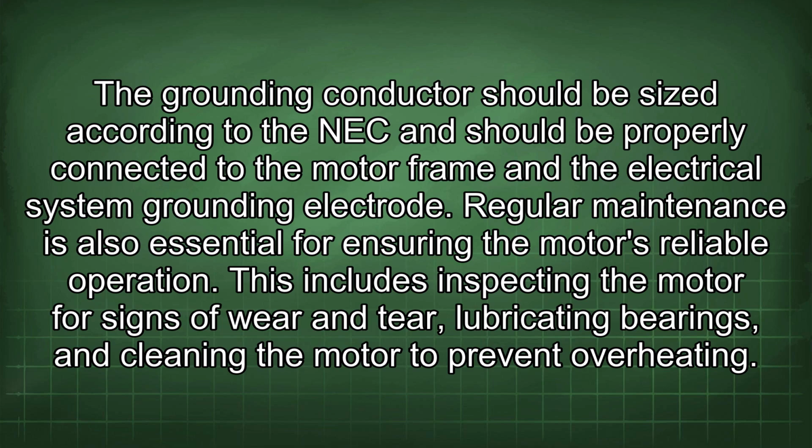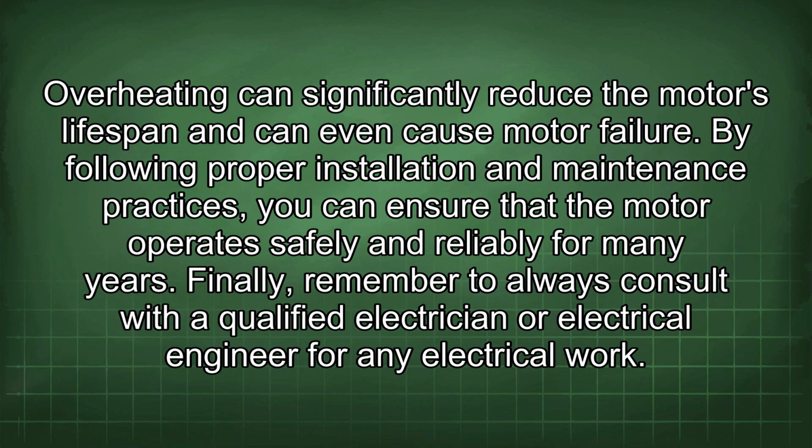Regular maintenance is also essential for ensuring the motor's reliable operation. This includes inspecting the motor for signs of wear and tear, lubricating bearings, and cleaning the motor to prevent overheating. Overheating can significantly reduce the motor's lifespan and can even cause motor failure. By following proper installation and maintenance practices, you can ensure that the motor operates safely and reliably for many years.